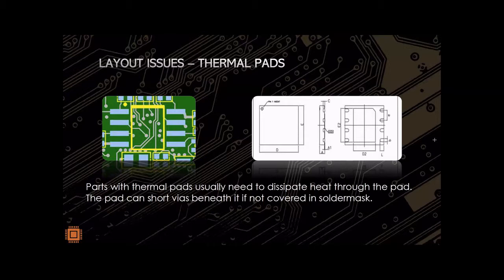And then at that point, we'll have to contact the fab house and warn them of this particular issue. So we'll give you the option of if either you want to place it as is, or if you want to go ahead and change it to a different component that doesn't have a thermal pad on that particular footprint.